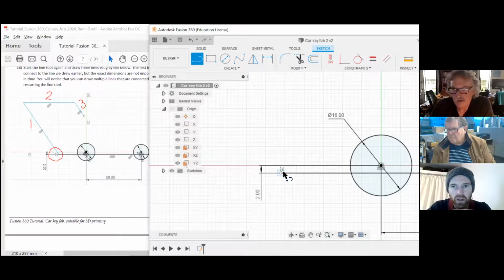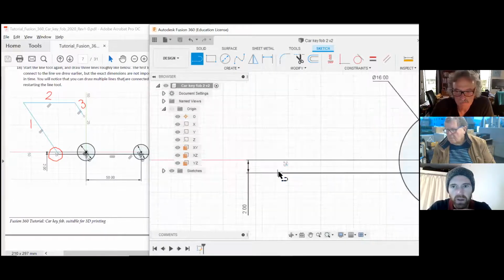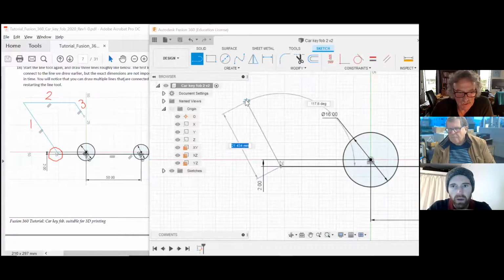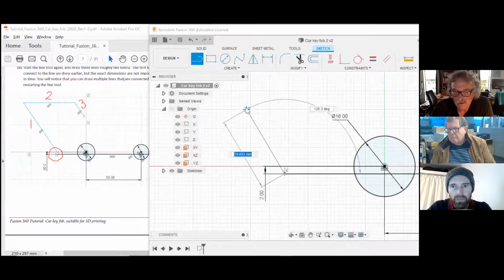So our first line, we want it to be coincident with the rear point of the line we just drew. So hover over there until you've got the blue box, and then left click. And now the line goes blue, but if we didn't create the constraint perfectly the first time, you can go and add it later, but it's good. Just back up the bus.